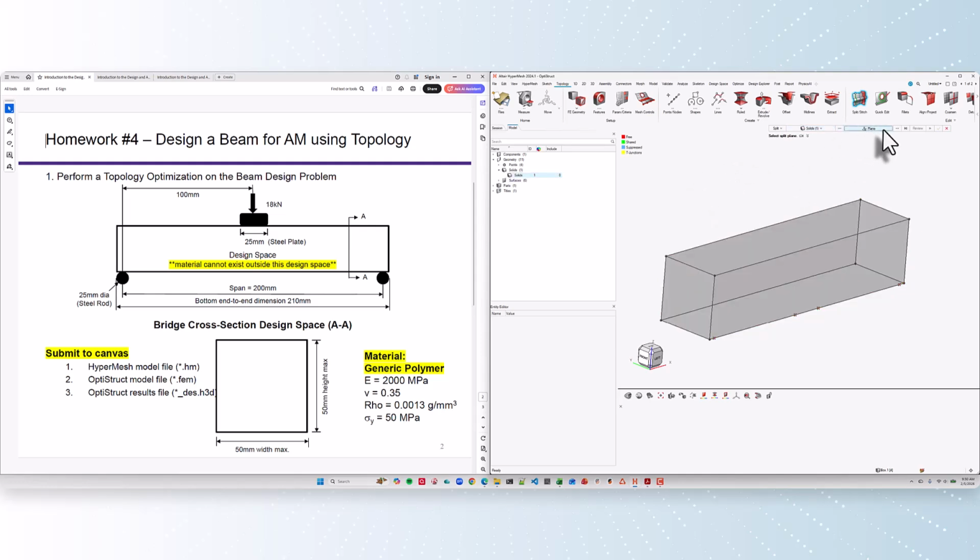And how do we want to split solids? I can click it again. I want to split it with a plane. Now, it'll snap to all kinds of points here, but it'll also snap to points that I made, which is why I made the points. So I want to create a trim right there, and I'll go ahead and play that.